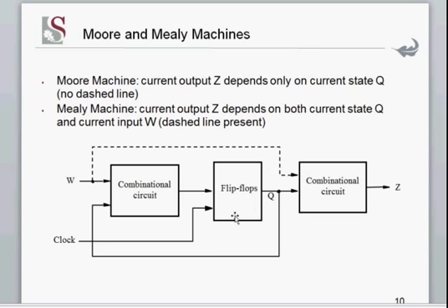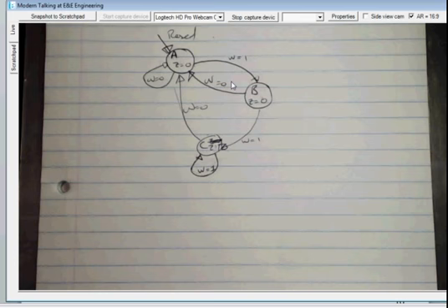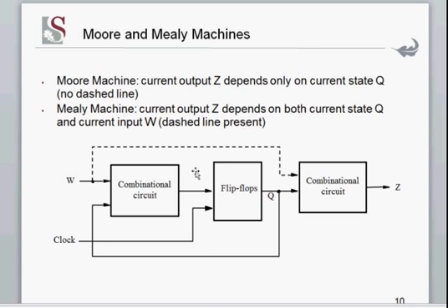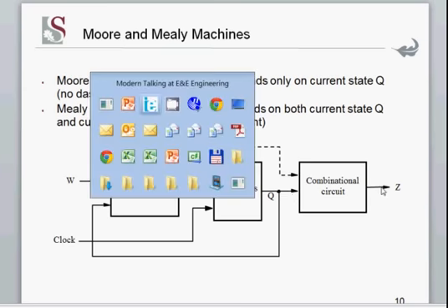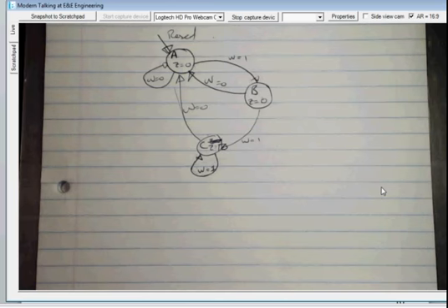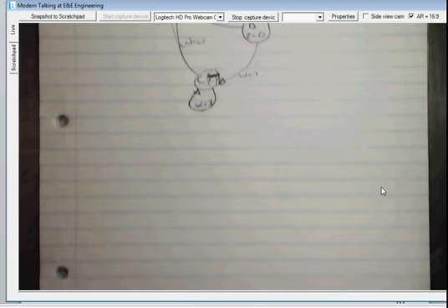As I said, the first thing you need to ask yourself is how many states. That'll tell you how many flip-flops. Then what we've done is we've drawn this diagram here, which tells you how it will transition between states. And all we need to do now is make a truth table to say, given certain inputs, what should the output be? Just a normal truth table. On this side the same. Given certain inputs, what should the output be? Just a truth table. So try to keep that in mind. We want to progress towards a truth table.